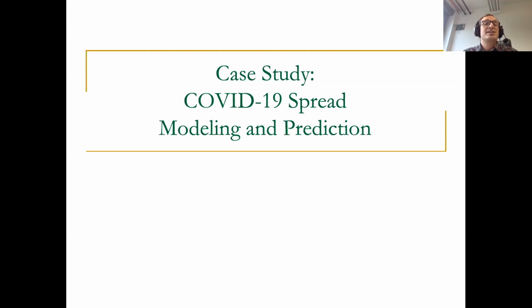So you need to have miss status holding registers, enough miss status holding registers, so you cannot say 4. And I think this was one of the issues with one of the simulators that I started out with, basically. The miss status holding registers was 4, but run-ahead execution actually generates many more requests than 4, let's say 40. So you need to increase the size of some of these structures to be reasonable, let's say. Now, if you've seen the Apple announcement a couple of days ago, maybe yesterday, I don't know exactly. I'm confused about the days, but now they have huge structures, right, in their machine. So in that kind of machine, maybe run-ahead execution can be useful potentially, but in a simulator that's conservatively provisioned in its structures, it may not work well.